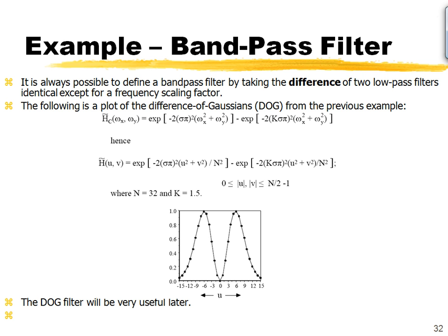Well, a simple band pass would be sort of two Gaussians, one shifted by the other. Okay. So I can design a band pass filter simply by combining two Gaussians. I can write out a band pass as being this in the Fourier domain. The first one is just a simple Gaussian.